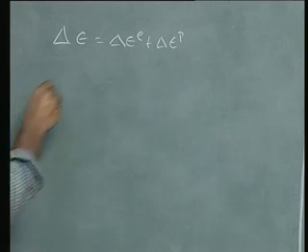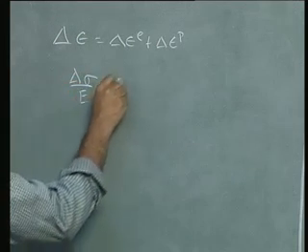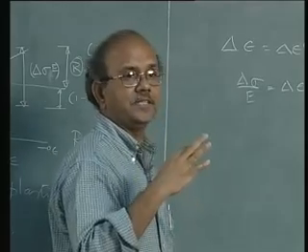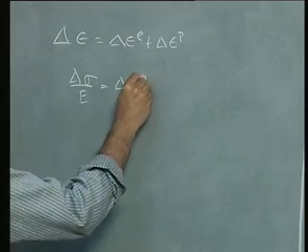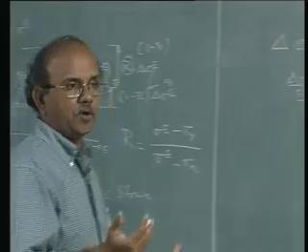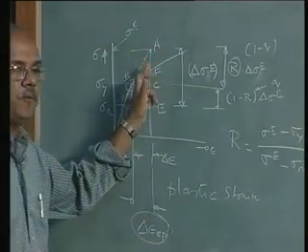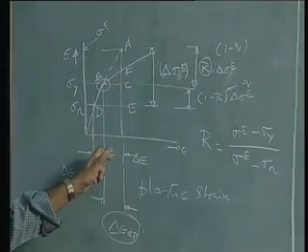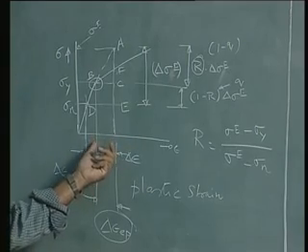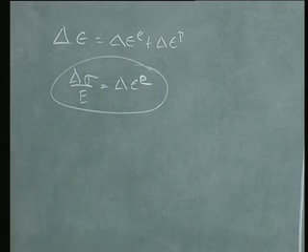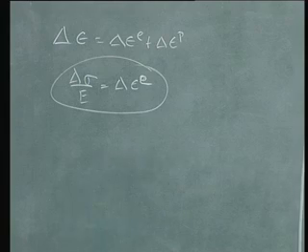Note this carefully, this is a confusion for many people: even in the plastic region, my elastic strains are written in terms of E. This is very obvious when you consider that when I unload from any point in the elastoplastic region, I unload in the elastic mode, and hence the elastic strains even in the plastic region are given by that. Is that clear?